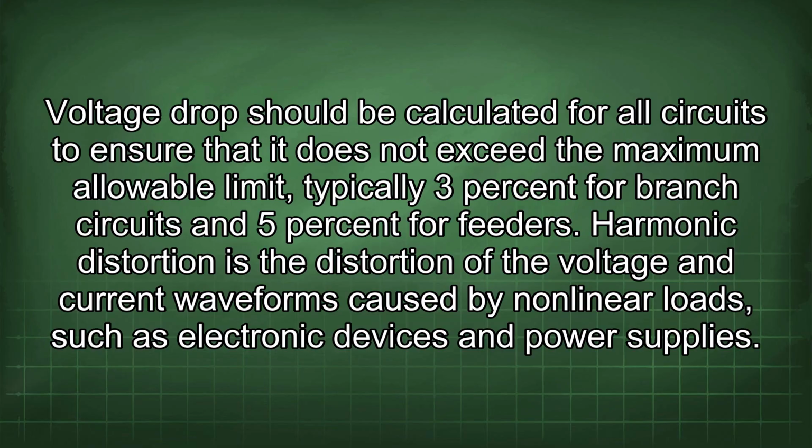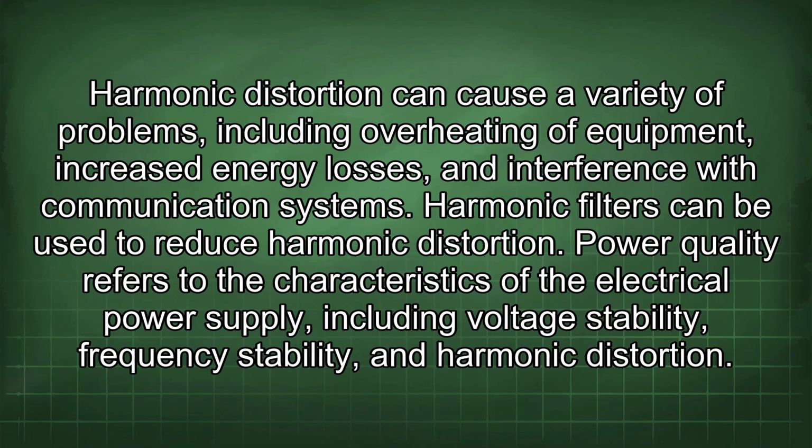Harmonic distortion is the distortion of the voltage and current waveforms caused by nonlinear loads such as electronic devices and power supplies. Harmonic distortion can cause a variety of problems, including overheating of equipment, increased energy losses, and interference with communication systems. Harmonic filters can be used to reduce harmonic distortion.